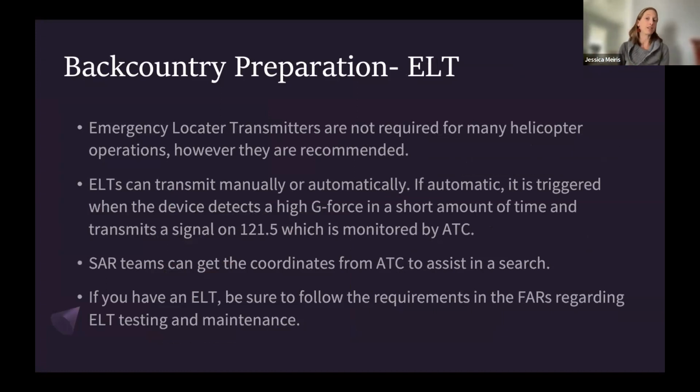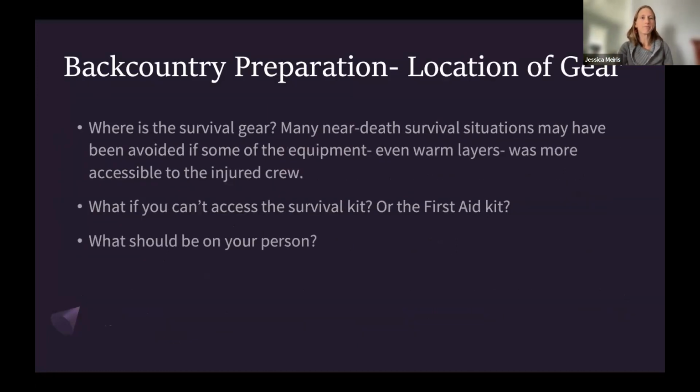And then lastly, the ELT on board. If you have an ELT, they aren't required for many helicopter operations, but they're a great idea. And there's both automatic and manually transmitting ELTs. If you do use an ELT, be sure to follow the requirements in the FARs regarding the testing and maintenance of those ELTs.